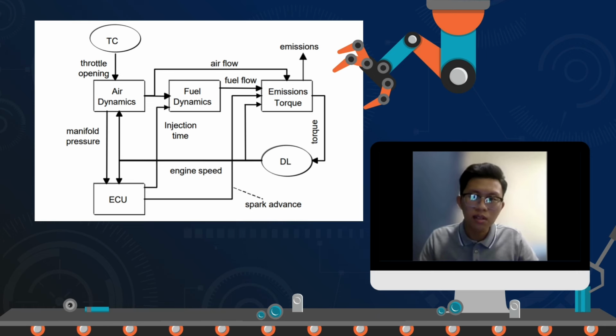According to this goal, the ECU module library offers a selection of several engine control strategies, which are mainly composed of a closed-loop lambda control and a model-based fuel film compensation.